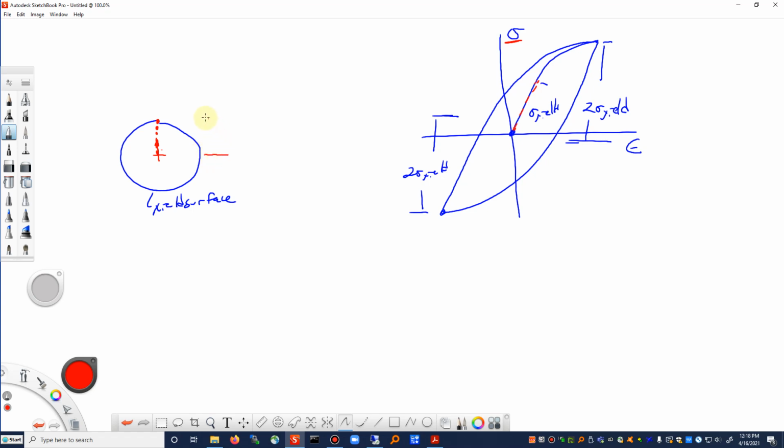So the radius of this is related to sigma yield. Now, if I'm in deviatoric stress, there's a coefficient that goes in front of that and so forth. Again, if you were to take the class in plasticity from me, we get into all these kinds of details, but conceptually, that's the correspondence in that one particular direction. Beyond yielding, we have the curvy part, and beyond yielding, maybe I can change to a different color, we continue on and we get up to, say for example, here. Then that would correspond to this portion. So that would be these points along this way.